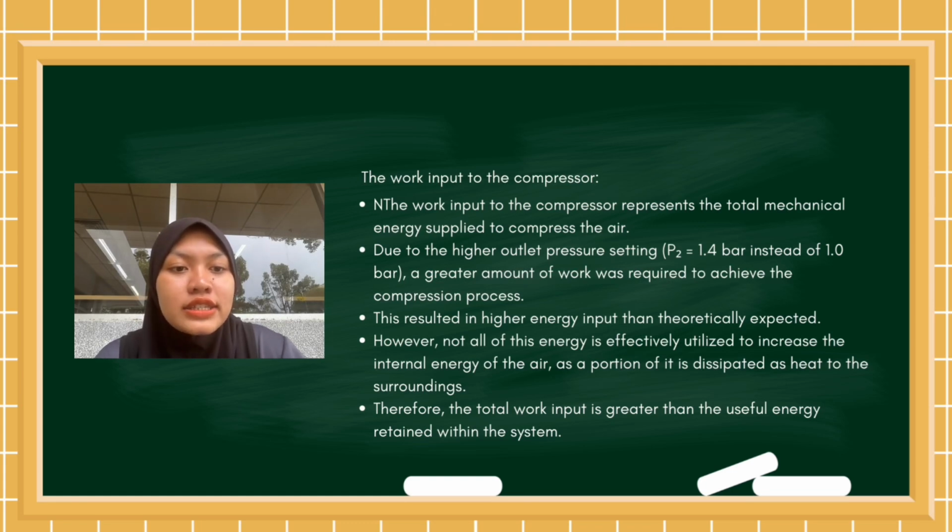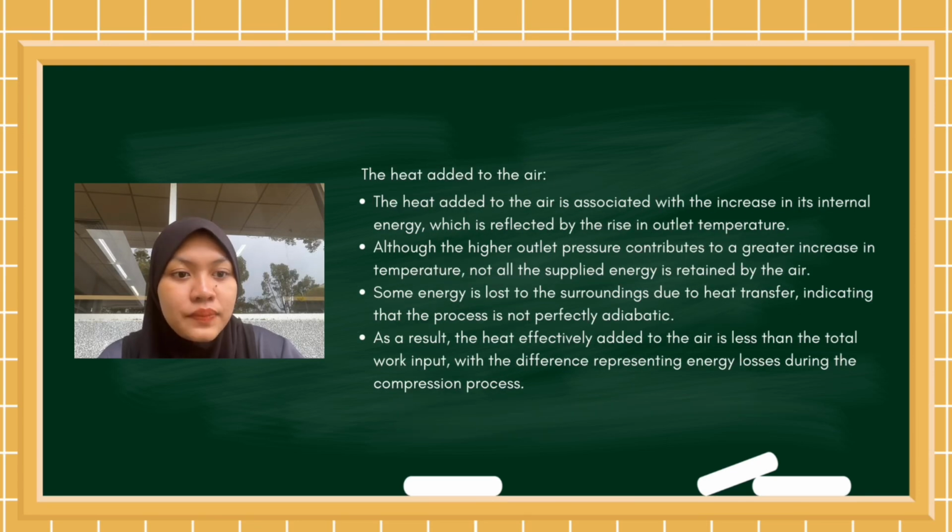The heat added to the air is associated with the increase in its internal energy, which is reflected by the rise in outlet temperature. Although the higher outlet pressure contributes to a greater increase in temperature, not all the supply energy is retained by the air. Some energy is lost to the surroundings due to heat transfer, indicating that the process is not perfectly adiabatic. As a result, the heat effectively added to the air is less than the total work input, with the difference representing energy losses during the compression process.